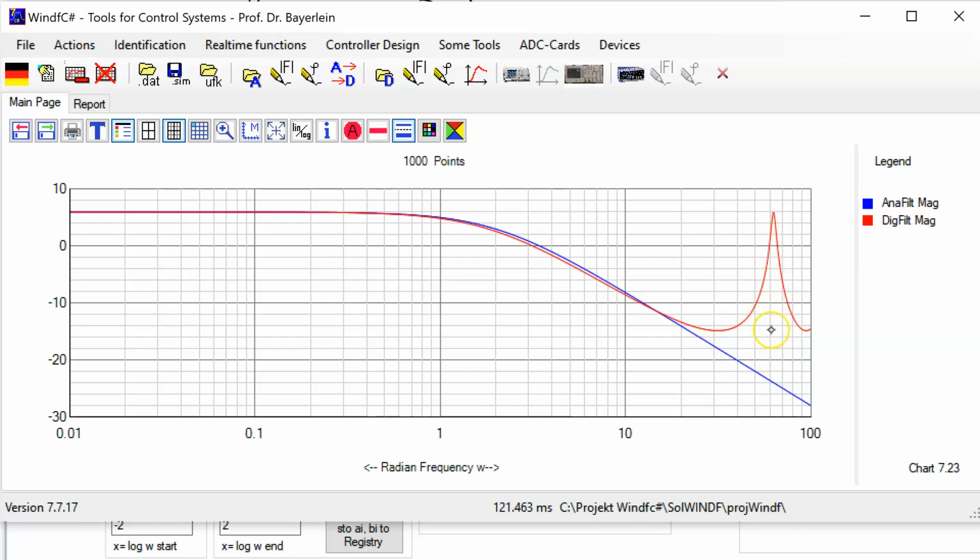That is simply said, that is here the frequency of, we have sampled with 10 Hertz. This is a frequency 10 Hertz. That is the omega axis here. So we have here in this position the 10 Hertz, and roundabout here we can define the Shannon limit, where we reach a limit where we can use this filter up to this point, and here we have aliasing with not recoverable input signals. So you see the first beginning, it is not bad.